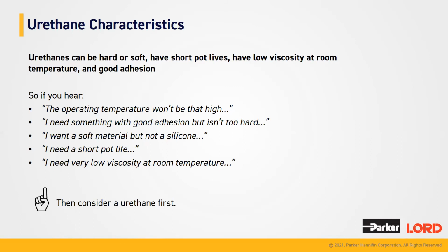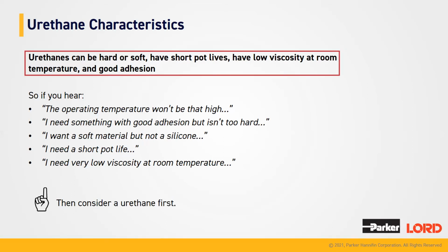Lord urethanes have a variety of characteristics that can be catered to many different customer applications and needs. Some properties that come to mind when thinking of our urethanes are they can range from soft to hard, they have a short pot life, low viscosity at room temperature, which makes them very easy to dispense and spread, and they also provide good adhesion.